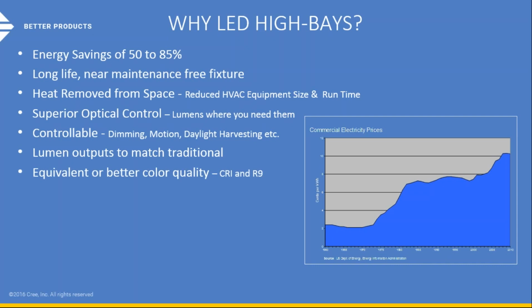Better light quality. So if you are new to the LED discussion, one of the benefits of LEDs is its color rendering capabilities. And largely that's driven through a palette of colors that are referred to within the industry based on numbers, like an R9 number in this particular case is an indication of how much red actually shows up within your light pattern or your light wave coming down from the fixture.